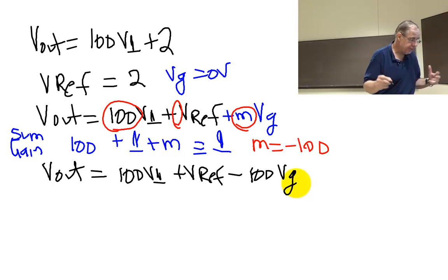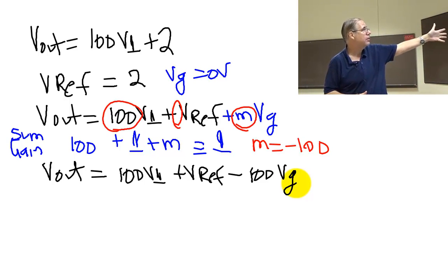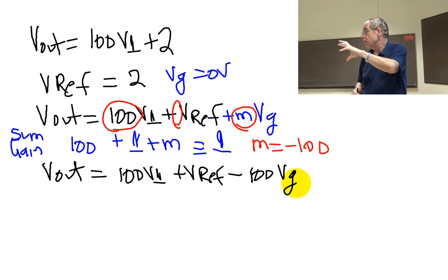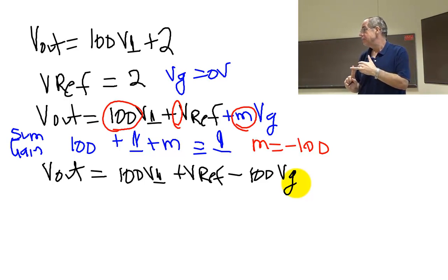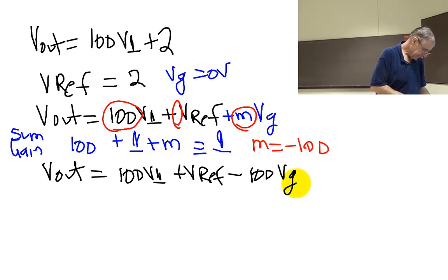It's the same equation. It still works, right? It still maps minus 20 millivolts into 0 and plus 20 millivolts into 4. It still solves my problem. Now I need a common multiple of 1 and 100. 100, right? I'm looking for a common multiple.